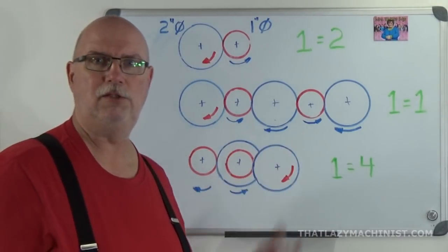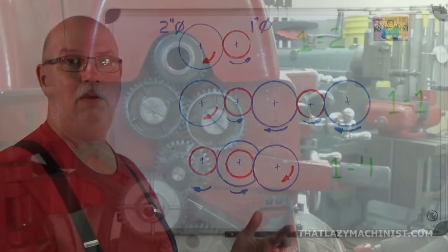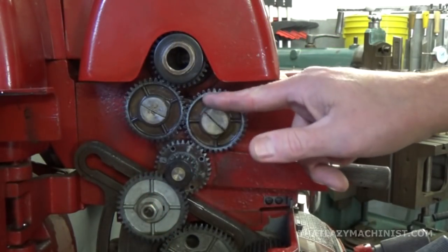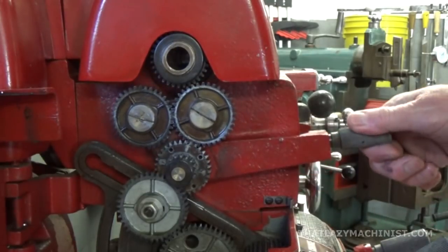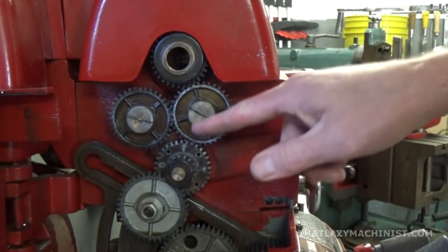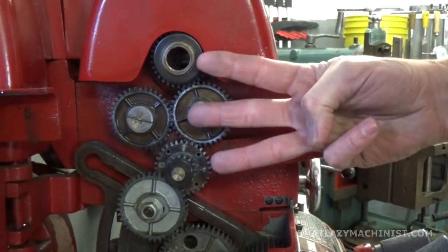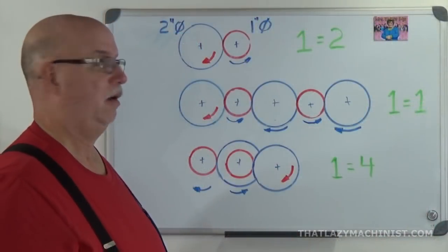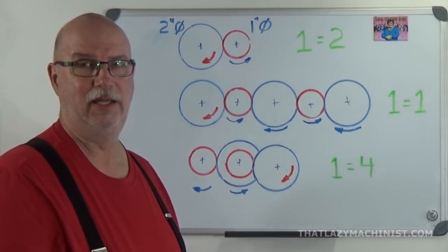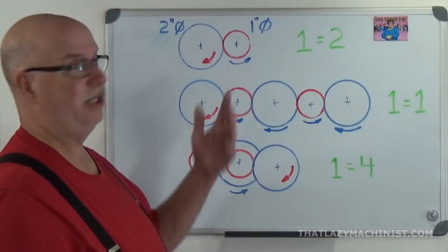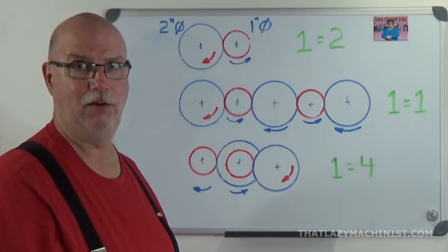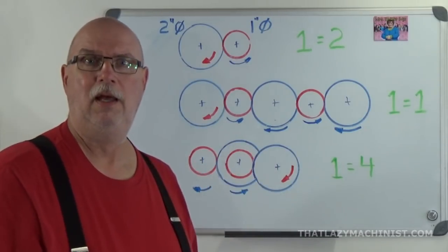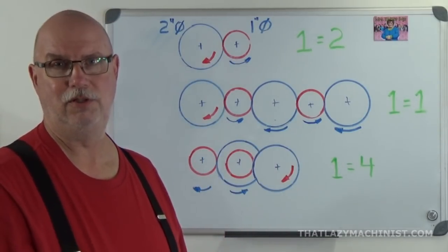And that is what we exploit quite often when we have examples such as a gear reverse on lathes. And all we're doing when we reverse the direction of rotation on a mill or on a lathe using a gear, well, is we're adding an extra gear to the mix, thus changing from odd to even or the reverse depending on what you're doing. So Lee, I hope that answers your question.